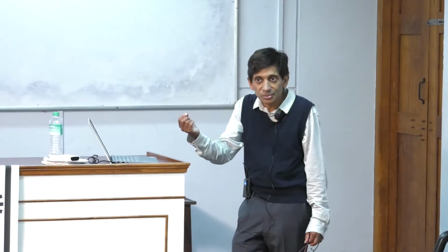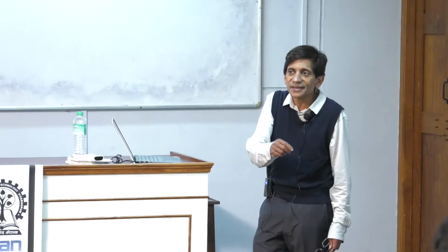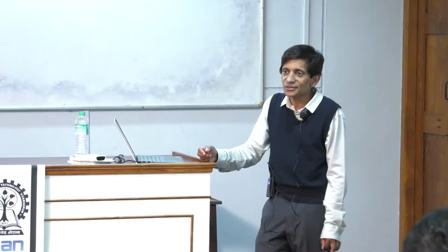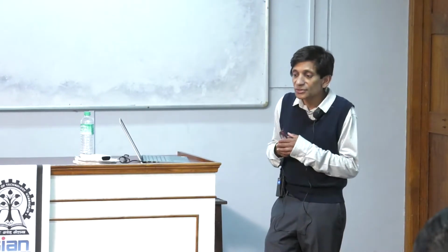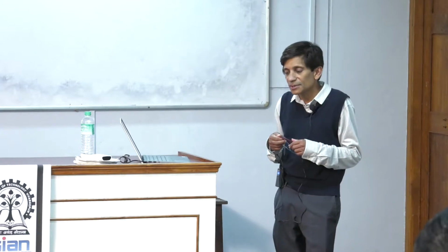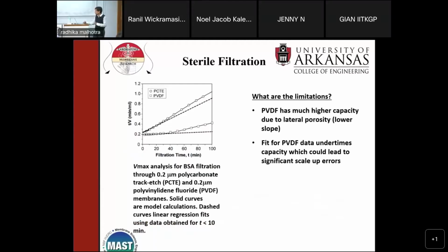It just uses a Vmax model. That's common in industry. But it assumes pore constriction. So in fact, if the feed stream you're looking at is not fouling because of pore constriction, you may get very wrong results, you see. So this is one of the things to be very careful of when you're trying to scale up, and especially if you're working for a biopharmaceutical company, it's quite important because people just use these models without thinking of the assumptions that went into them, okay?